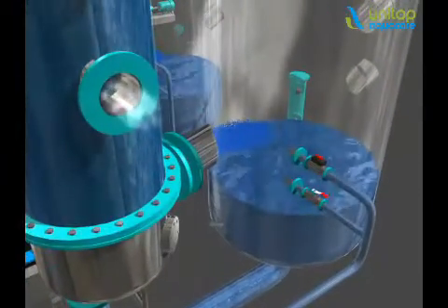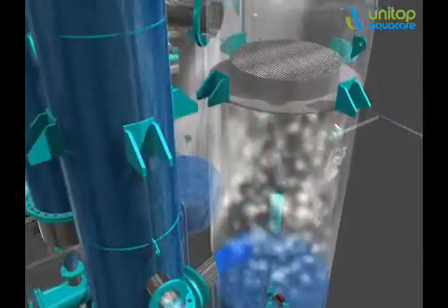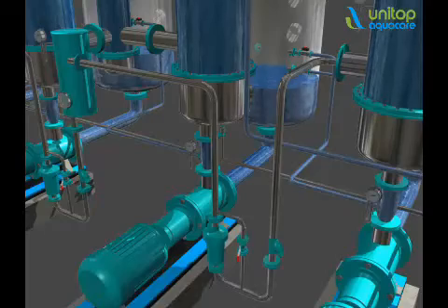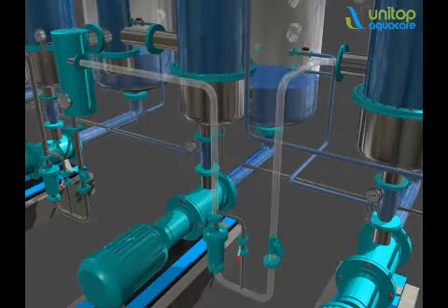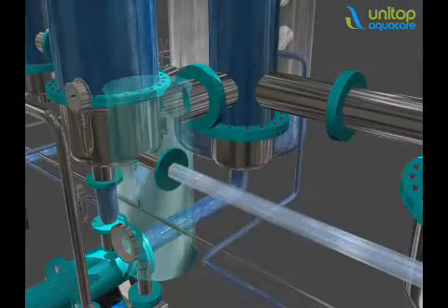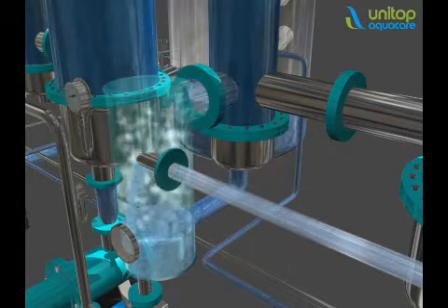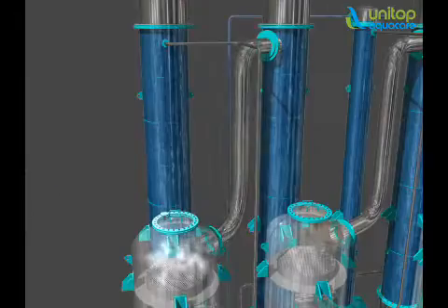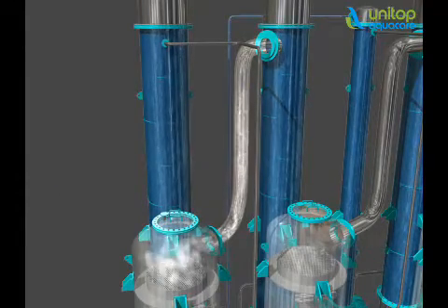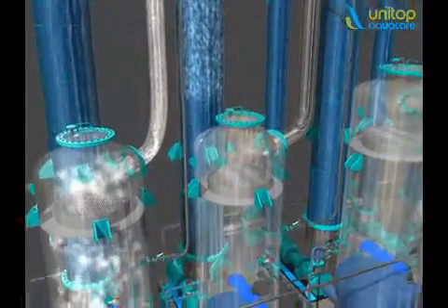Start supply of steam to the heater at the required pressure. The feed gets heated and flashes in the vessel due to lower pressure. Preheaters use the flash vapors of the hot condensate to preheat the feed close to the boiling point, thereby saving steam. The vapors generated by flashing of the liquid are taken to the next effect due to the lower pressure and used for evaporation in the next stage.